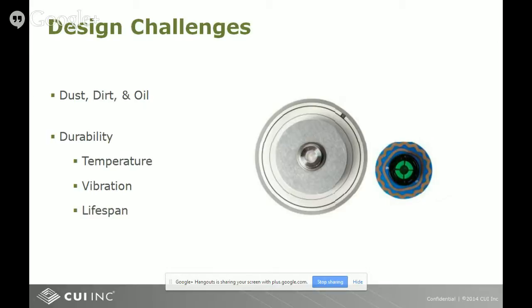The optical has a challenge because of line of sight, obviously. And then other issues, certainly oil for lubrication in the motion environment. But then there's also applications where the entire enclosure has to be submerged in oil, and those obviously pose some real challenges to the designer in where they're using that encoder.